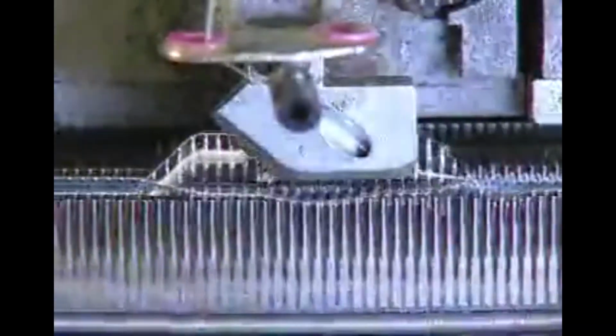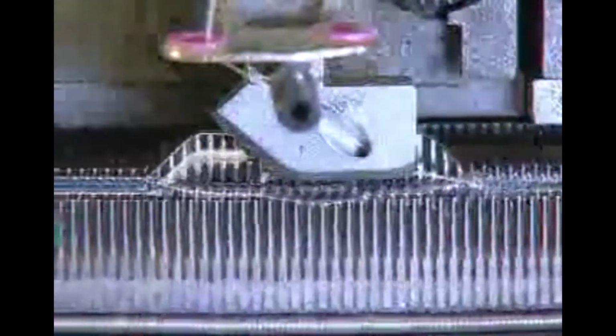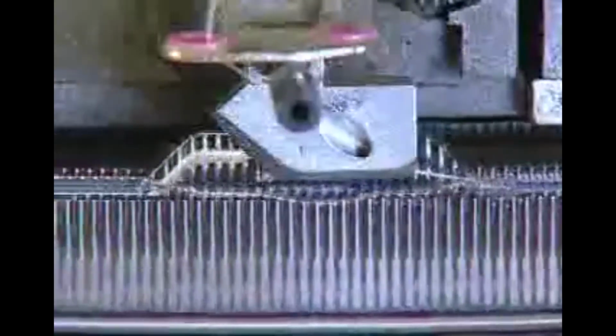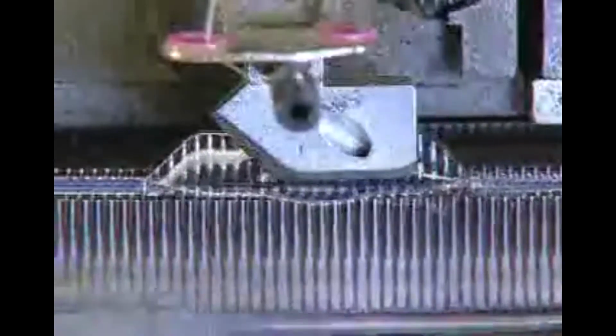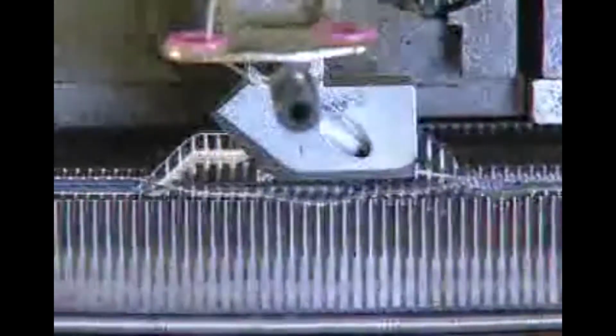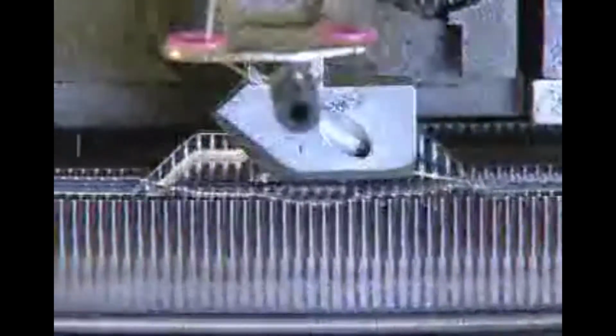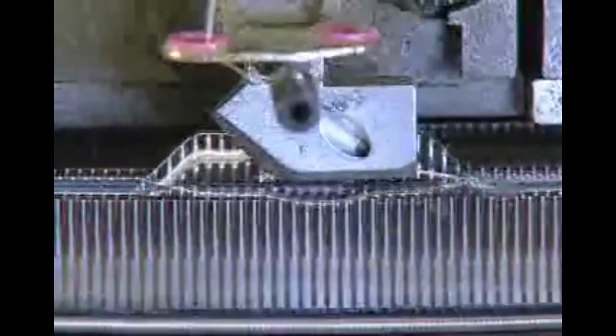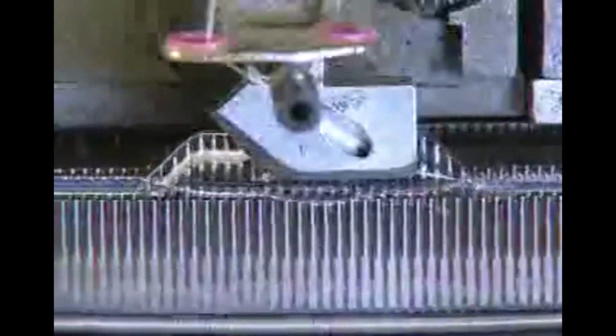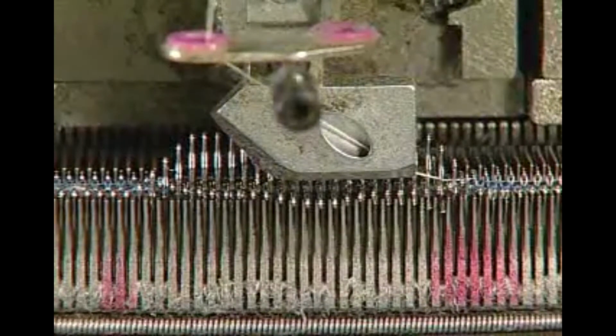Whether circular knit or flatbed machines are used to produce double knits, there is some variance in how needles are employed to create this fabric. Both sets of needles can be used at the same time or at different times, but they don't touch or hit. How are they positioned and activated to accomplish this? On a knitting machine, needles are gated, or spaced in the dial and the cylinder in relationship to each other.